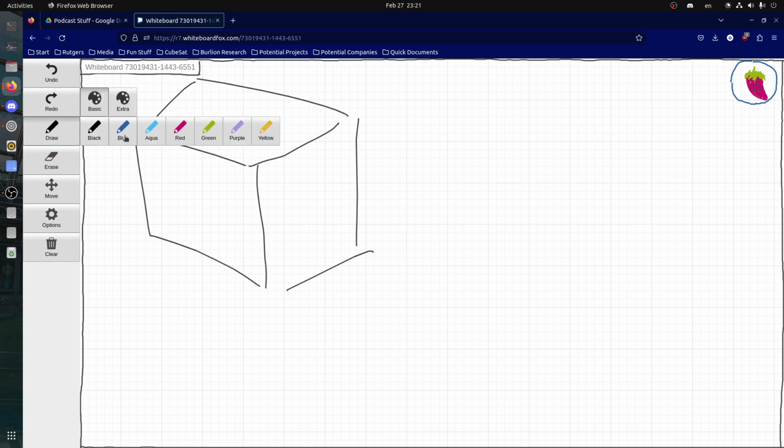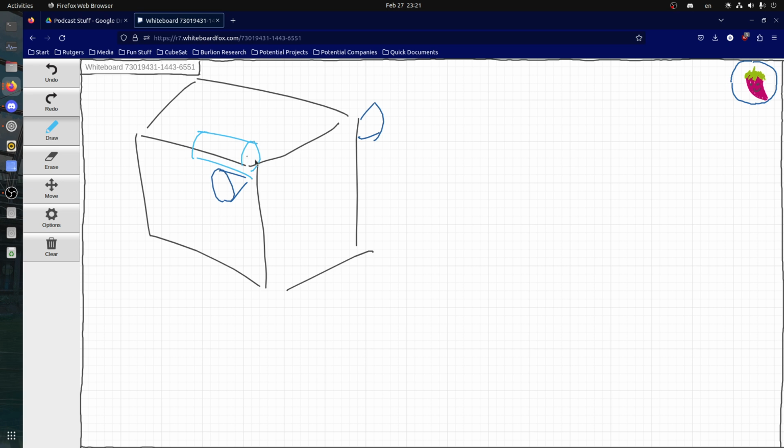The second one is called gas thrusters. So these work based completely on Newton's second law. Usually they come in pairs. I'm not going to draw all of them because it's a pain, but usually you'll have a pair of thrusters. They call it cold gas because there's a canister of gas and it's piped up to all of these, and using a valve that's controlled by the control system, you can let the gas out, and when the gas escapes, it has some momentum that it carries away, and your spacecraft will spin with the opposite momentum.